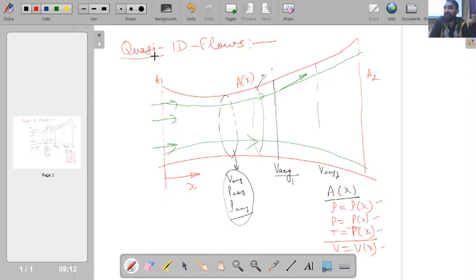The area velocity relation gives us the variation of velocity with area: when area is changing, how velocity changes for different flow situations. These are the fundamental basis for studying compressible flow through variable cross sections, with ultimate applications in rocket engines, gas turbine engines, and supersonic wind tunnels.